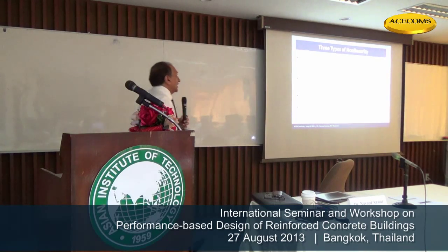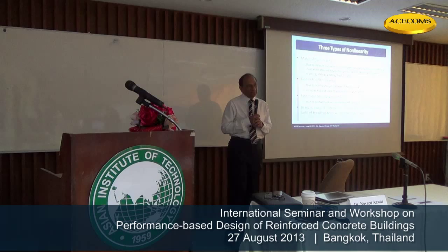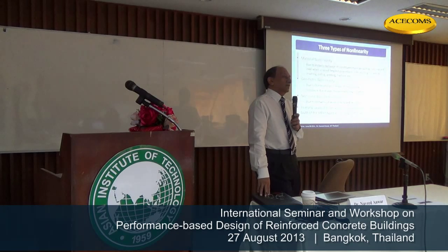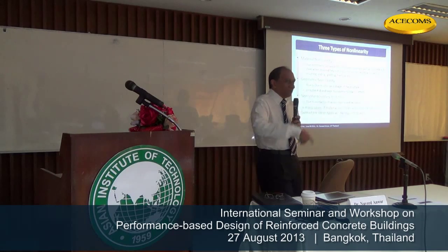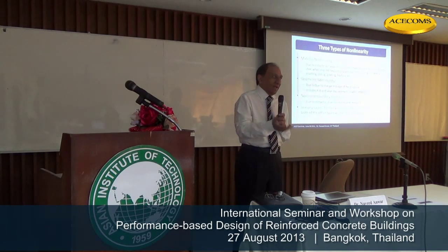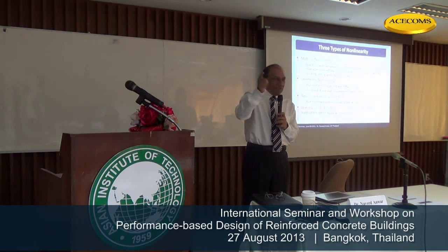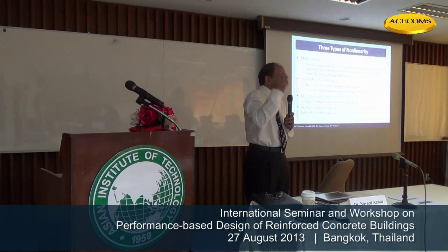Types of nonlinearity: we have material nonlinearity, as I mentioned, I've shown you a little bit, geometric nonlinearity, and then nonlinear boundary conditions. What does it mean, nonlinear boundary conditions? Soil is also a nonlinear material. We often forget about that. Foundation is not just a foundation. Foundation means a pile cap or a footing, and then soil below that. Normally in our mind, foundation means a line with a few hatches, which means a fixed foundation or pinned foundation, and that's what we think. But actually that's not the case.